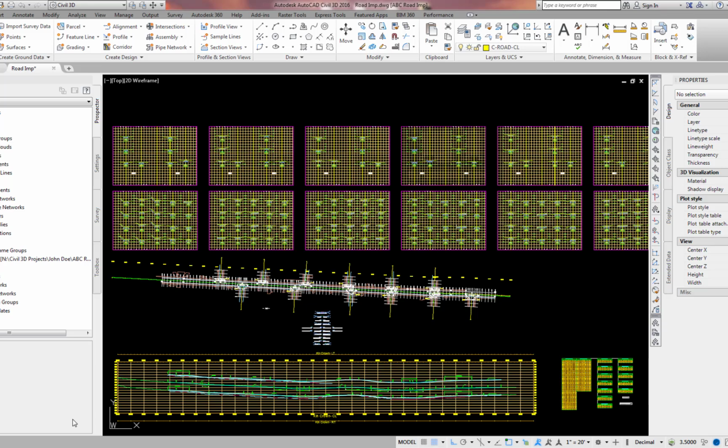Profiles of existing driveways are prepared to determine the extent of driveway reconstruction that is required to eliminate vehicle dragging after the new improvements have been constructed. Driveway sample lines are used to indicate locations where the driveway profile sections will be taken. Each alignment will have its own group of driveway sample lines.